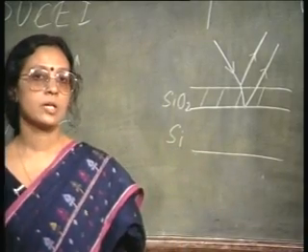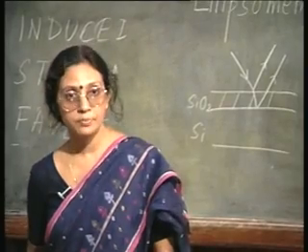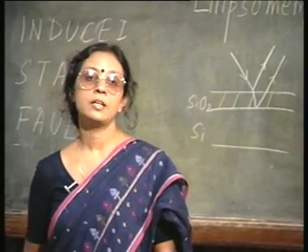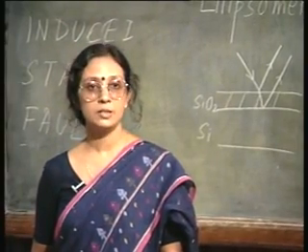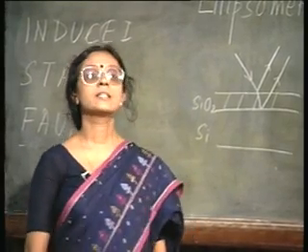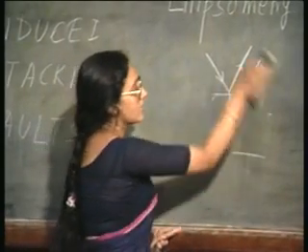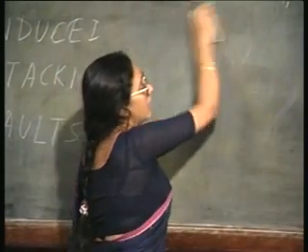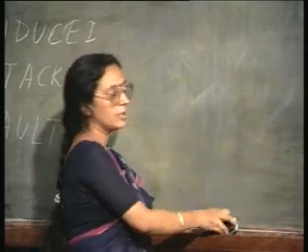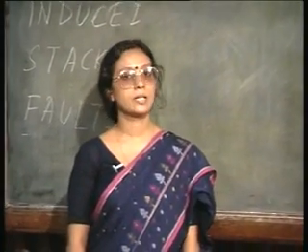In the laboratory, however, we use another very simple and electrical method of determining the oxide thickness, and that is done simply by taking the CV characteristics of the oxide. You know, if one has a MOS capacitor, then in the accumulation region, the capacitance of this MOS capacitor is going to be the oxide capacitance.